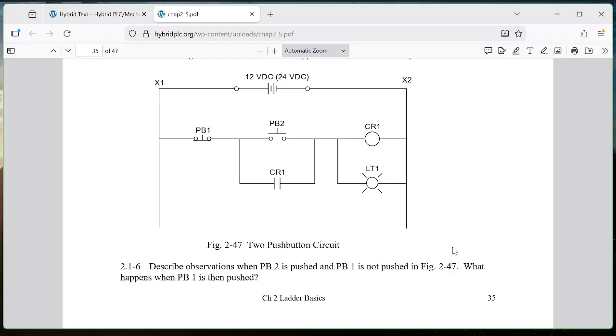Now, what else about this circuit is interesting? What if you turn off the power? An electric storm comes across, you have a power dip, and power comes back on. It is in the off position, right? So you have to restart it after a power dip. Why is that important?